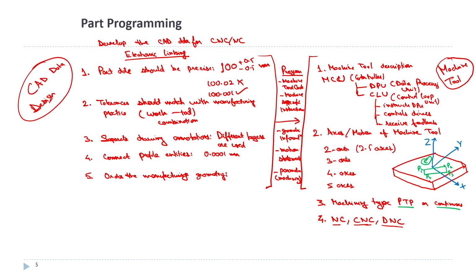Communication in a distributed numerical control system is usually achieved by using a standard protocol, generally TCP/IP, using the internet facility that we have, or within a system or your server, it could be an intranet itself. A central computer has various functions: it stores NC programs, it downloads these programs to any number of CNC machine tools, it performs the feedback task for them, and it provides communication between various components of the overall distributed network system. The major advantage of the distributed network system is that it can be centrally monitored.